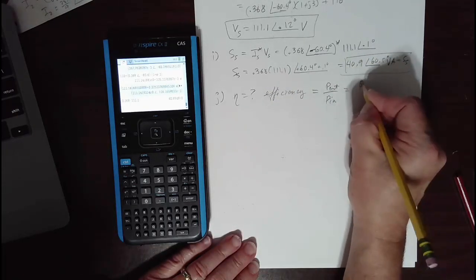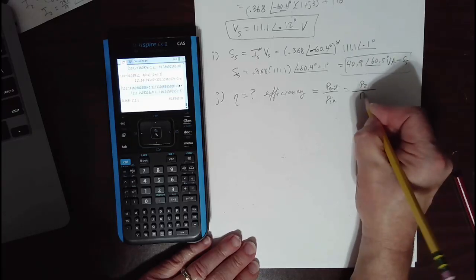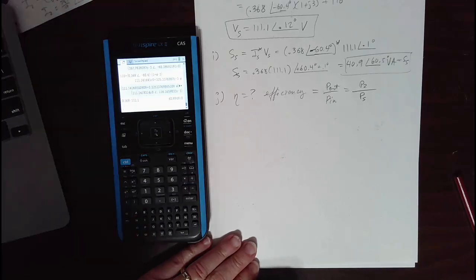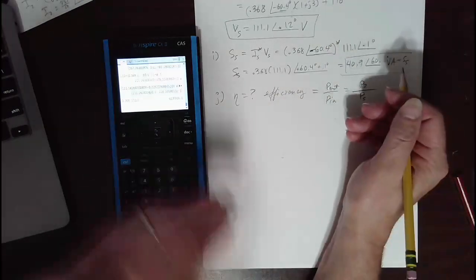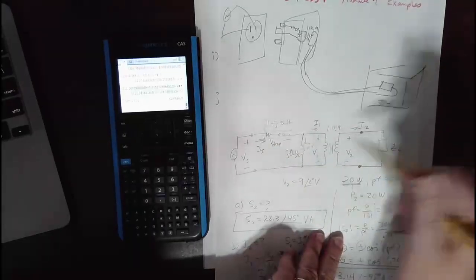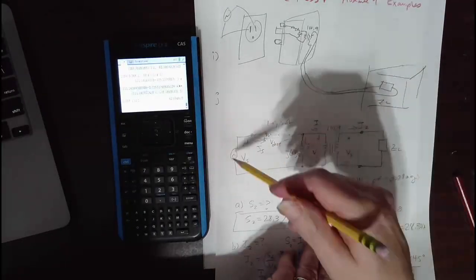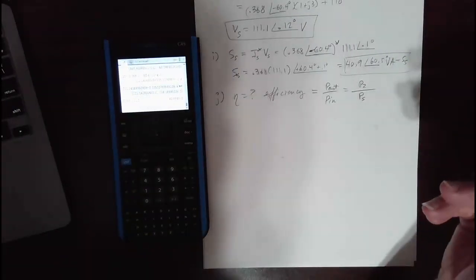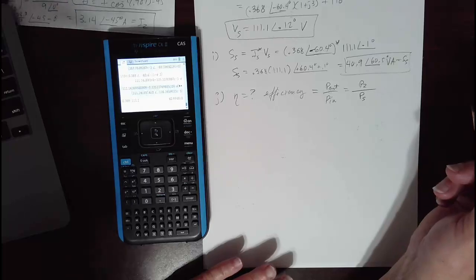In this case, P2 is the power out, and the power of the source is the power in. So it'll give us the efficiency of our transformer. Since we're using a realistic model, it has some resistance in it, so the power in should be a little bit more than the power out, right? The ideal transformer doesn't lose any power, but my realistic version should lose a little.